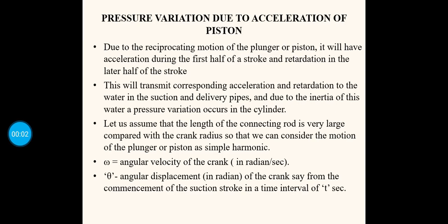Hi dear students, this is the third part of the subject ME 206 Fluid Machinery, that is reciprocating pump. Due to the reciprocating motion of the plunger or piston, it will have an acceleration during the first half of the stroke and retardation in the later half of the stroke. We all know the working of the reciprocating pump. I have explained in the first part.